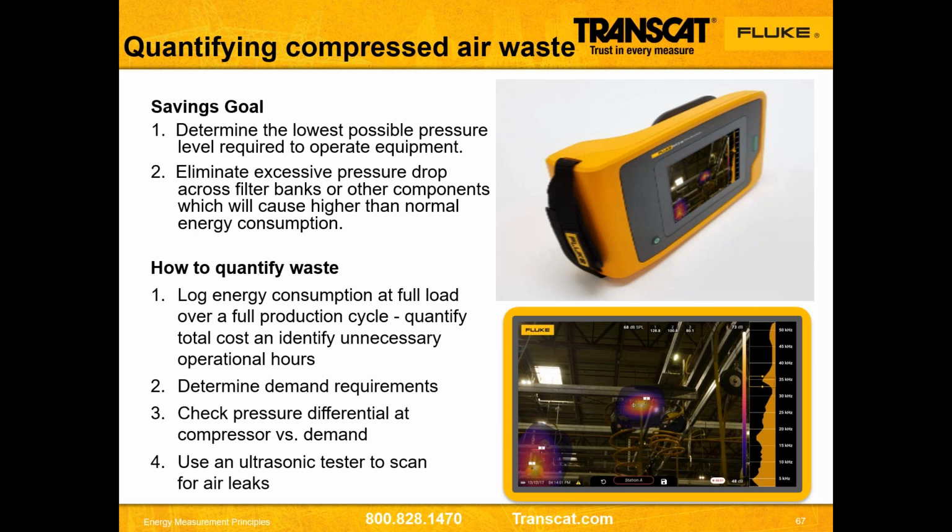I don't have to know what they sound like. I don't have to put headphones on. I can visually see them, so I can identify where they are and whether they are a real leak or not. And how we do that is if we move and the leak moves, it's a reflection, which I can't pick up with headphones. But if it's a real leak, it stays put when I move, and we can quantify and tag it, fix it, then shoot it again and know that the leak went away.